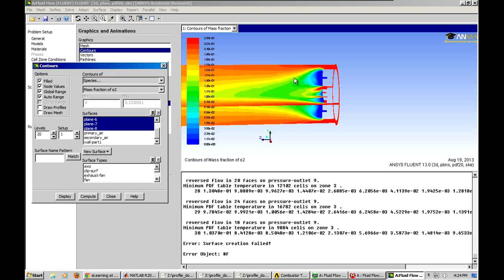It's being burnt completely, whereas before, if you recall, we had oxygen coming in through the inlets, but then it was being used up completely right as it entered the chamber, and there wasn't enough air for the amount of fuel. A lot of times you'll even have an excess amount of air for your fuel, even 10-15%. That depends on the combustor, depends on what you want to achieve. You can do things like lower the NOx, you can lower the CO2 by manipulating those numbers, and of course the design of the combustor.